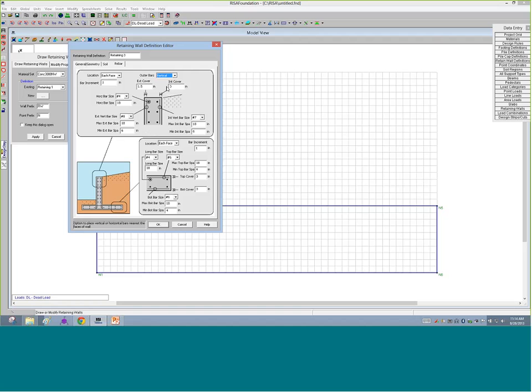Now that's going to change your D values, so that's kind of an important one to make a decision on if you're real tight with your design. We've got the external cover and the internal cover, oftentimes differing, so we can have the ability to do that. Now the program is just going to put the bars in here based on what we tell it. So we may want to choose some bars wisely, maybe number 5 for the horizontal bar at 18. We're using external and internal bars.